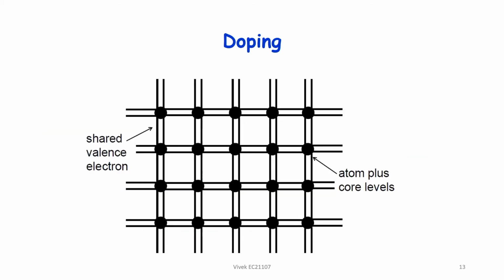Okay. Now, the interesting property of semiconductor is the ability to dope it. For example, for simple silicon, we have 10 raised to power 10 electron hole pairs per cubic centimeter. So, of course, its conductivity will be very small, but you have the ability to dope it. So that means you can vary this doping from 10 raised to power 10 to 10 raised to power 20. So the conductivity can be varied over a range of 10 raised to power 10. So there's a huge improvement in conductivity.